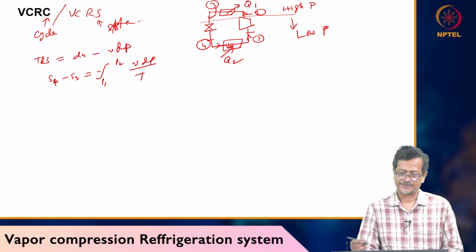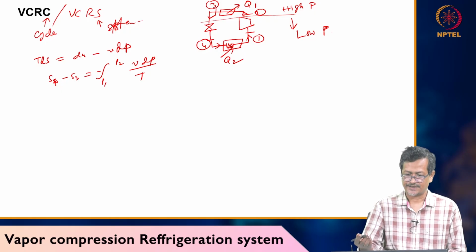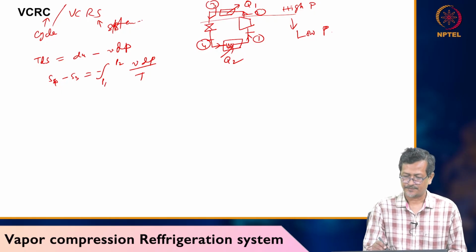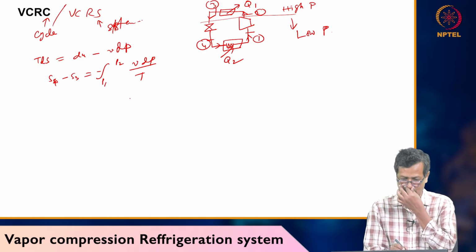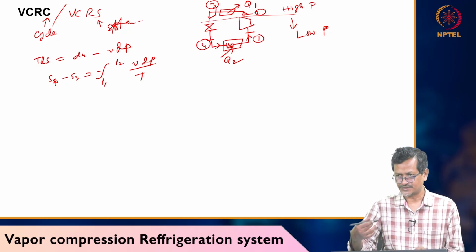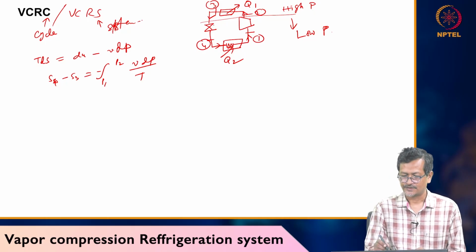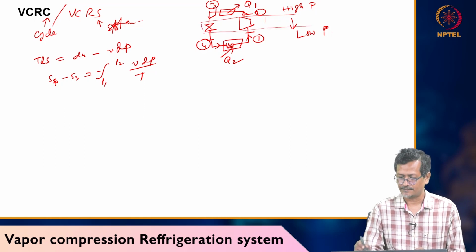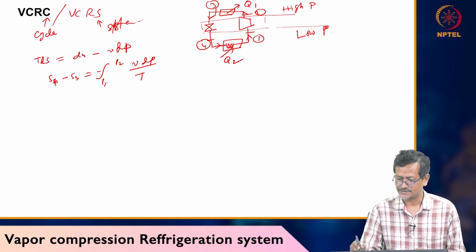Okay, upper part high pressure means after compression the pressure is high, and the high pressure will be there till the throttle valve. After the throttle valve your pressure changes to lower pressure. So pressure change is happening in between these two, and below this one is low pressure.